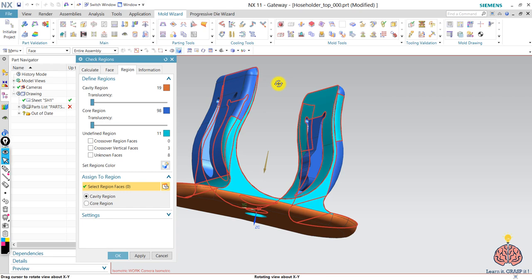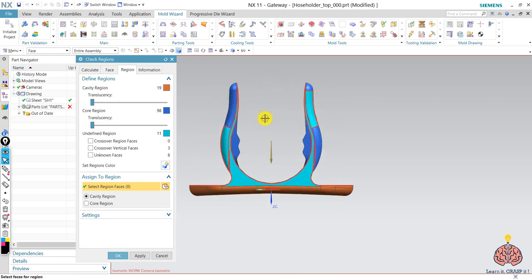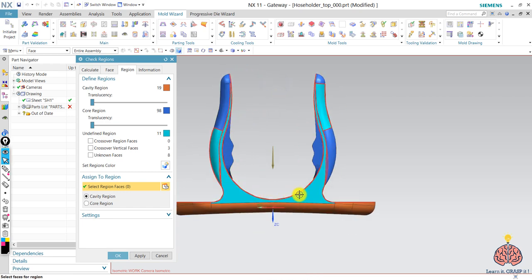If the core came from the top, like if we looked at this part, it will all be metal. Let me explain it for you. So while this thing is getting ejected to the bottom side, these things will open up because the material of this plastic has elasticity. That means that it can deform and get back to its original form again. So there's no problem with this undercut.